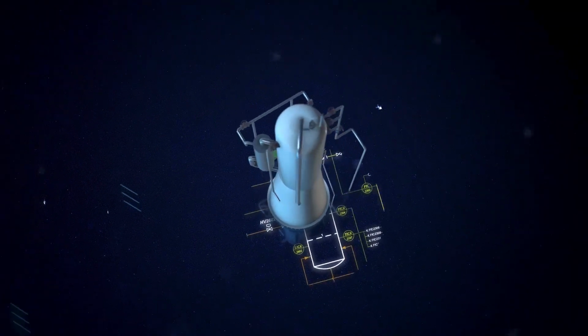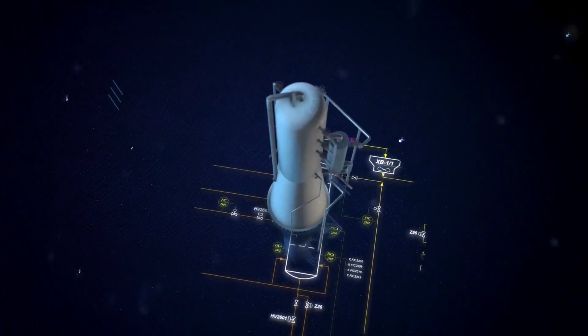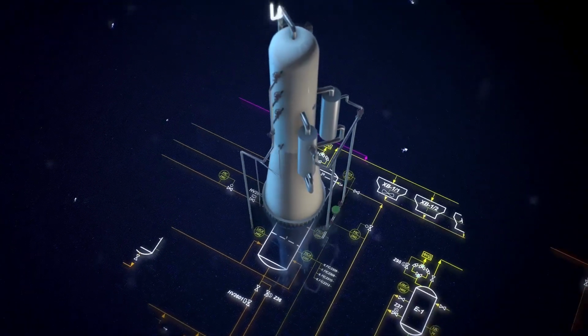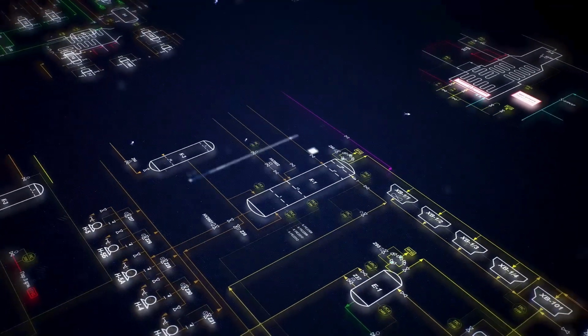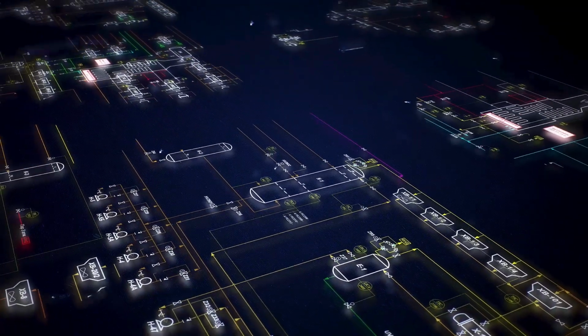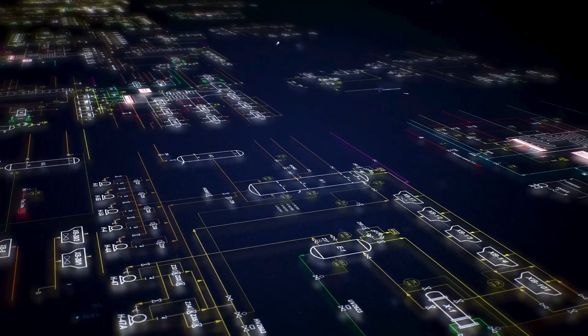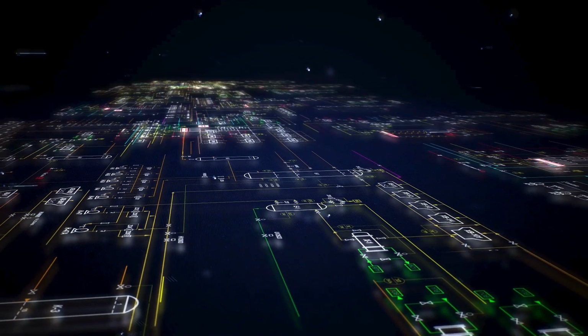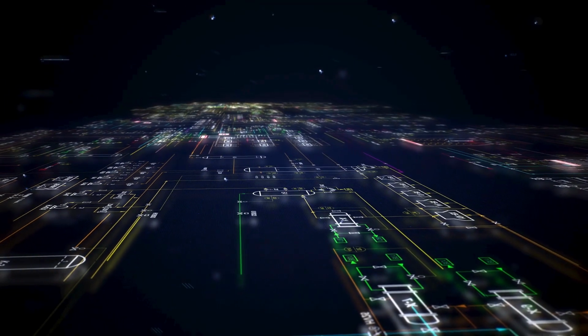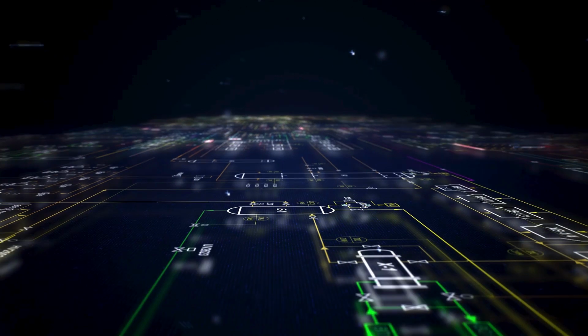The hydraulic model of the process is based on the calculated technological scheme. To achieve high modeling accuracy, the technological scheme must be as complete as possible, including not only elements of the main technological chain, but also auxiliary lines such as drains, air control instrumentation, smoke exhaust fans, oil systems, and others.